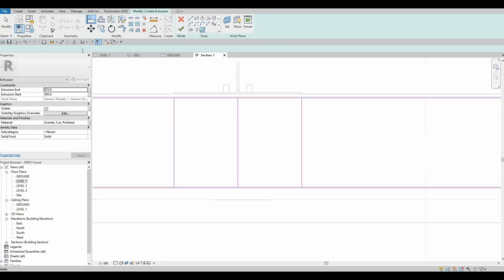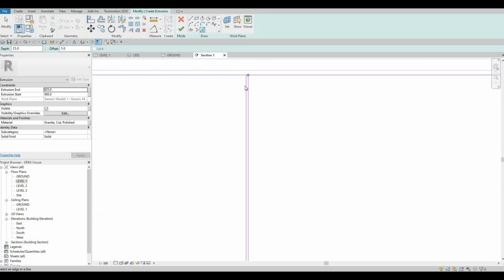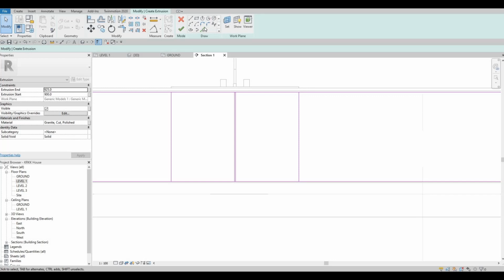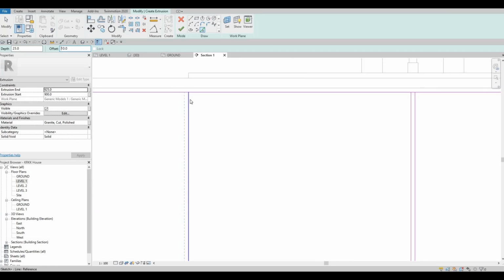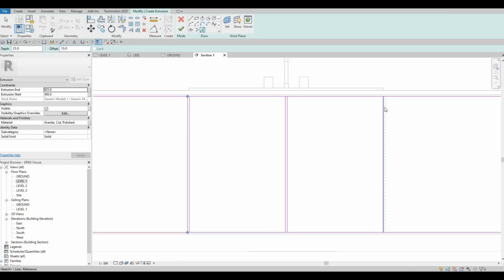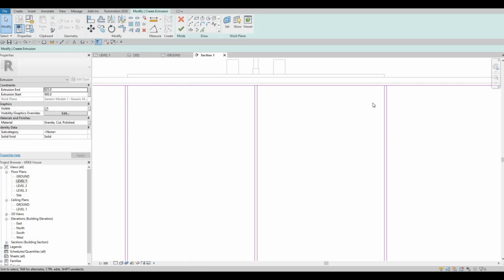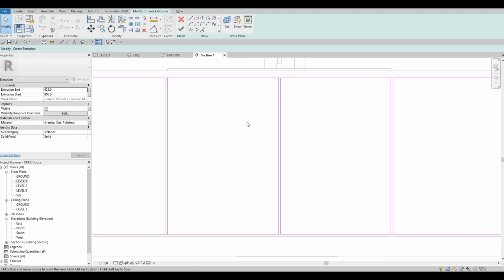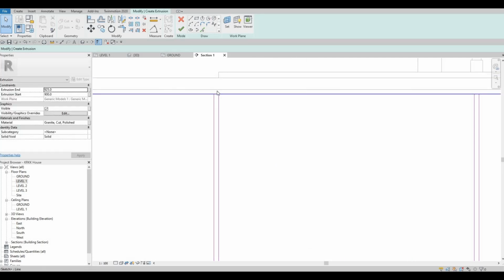I'm going to select this pick line and then click on 5 offset from the middle, and then delete the ones in the middle. Press escape and delete the ones in the middle, and then here, pick line, I want it offset 10. So maintain the 10, and then we need to click on split face later on, or split line.